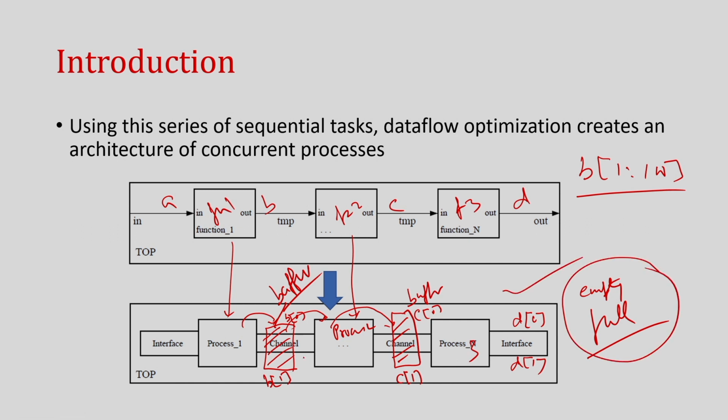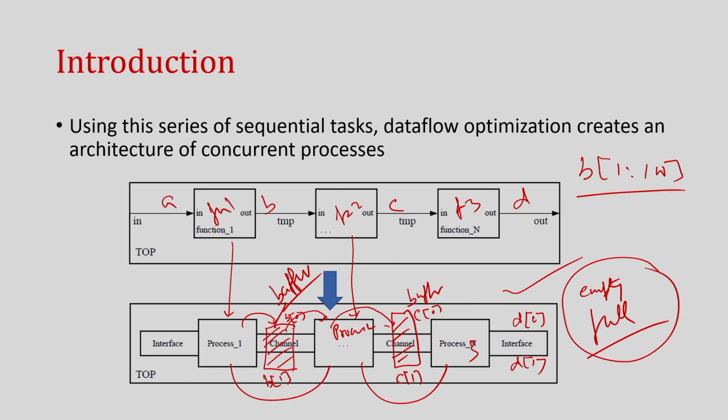So, there will be some handshaking signals between these two processes, using the buffer between these two processes, so that there is no race condition, deadlock, or starvation. Everything will be controlled by this synchronization signal. So, the RTL that will be produced by the high level synthesis tool is in this form, and its execution is completely different from the actual C code, because in the C code it is going to execute sequentially, whereas here it will actually happen in parallel, right.